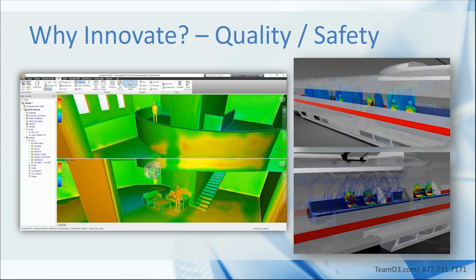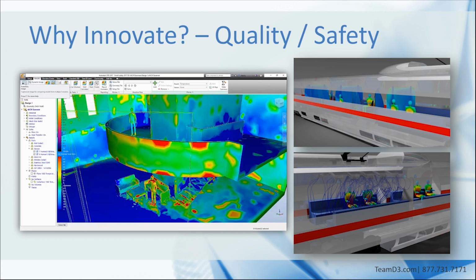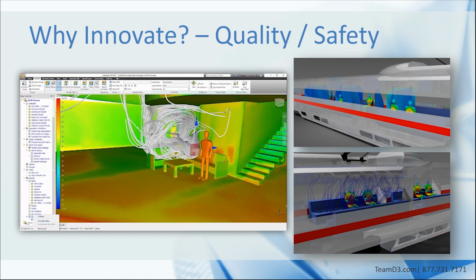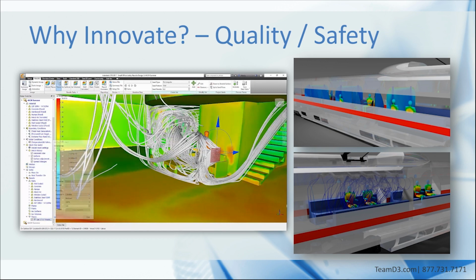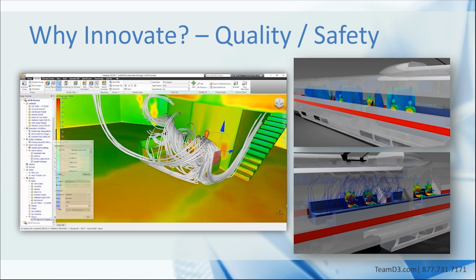Knowing how long the air spends inside the space helps us to avoid stagnation zones that may have inadequate fresh air or uneven temperatures. Simulating different times of day and different times of year ensures our spaces are always comfortable and healthy. They can be measured empty or at maximum capacity. There's some very specific outputs available from CFD related to the comfort of its occupants, such as predicted mean vote and percent persons dissatisfied.